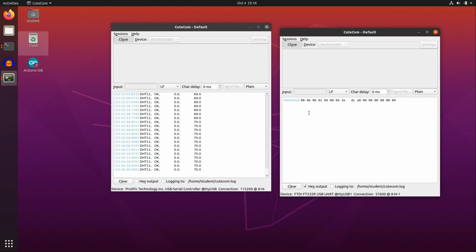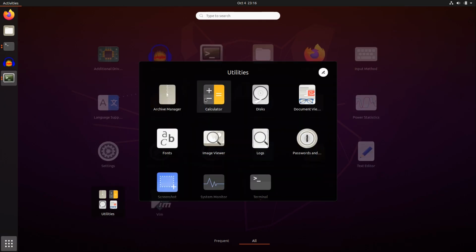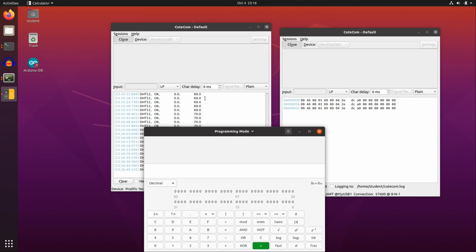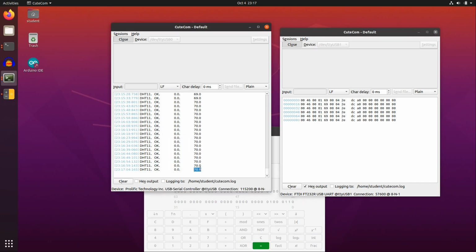The temperature that is reported is here. So 46 hexadecimal should be 70 degrees in decimal. And there we have it. So in your implementation, if it shows 46, 70 should be printed out. Right, this is just a different presentation. This is decimal and that is hexadecimal. These other numbers, they are not that important as of now. That we will handle in the chapter about ADC later in the course.